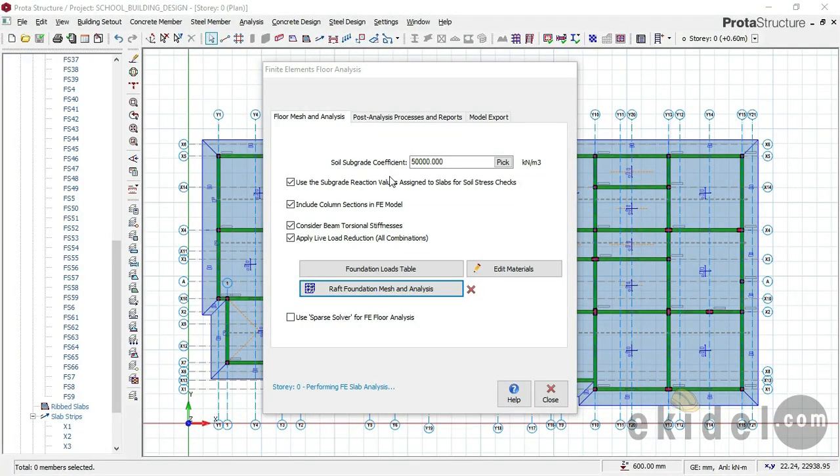Okay, and then you will also see what they call positive moment and also negative moment. Leave those two values as they are, and just input your soil bearing capacity, which I have said already in our part 1: before you make a choice for a raft foundation, your bearing capacity must be below 75 kilonewton per square meter. Once it is above that, you have to use a pad foundation or a different kind of foundation. But once it is below, you have to consider using a raft foundation or a wide strip foundation.